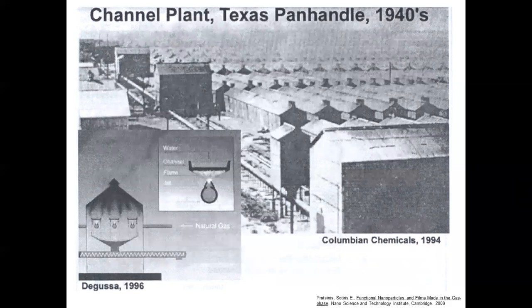And interestingly, the burners on here are scaled to be rather small. The flames generally on a pyrolysis system are measured in a few centimeters, so typically these would be like a lighter or something like that. You'd envision that these flames would be rather large. There's certainly a large amount of flames, but each individual flame is small, and there's a number of these flames, and we're going to see the rationale for that later in the presentation.